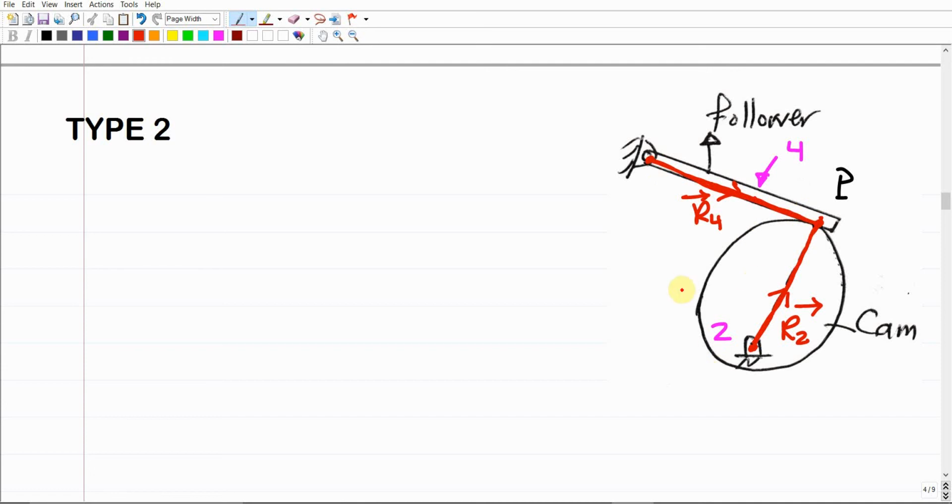So we're going to end up with a loop, but this loop is still open. To close the loop, we have to set up, or assume, this R as the R1 position vector. So we end up with a loop that includes three position vectors: R1, set up between the two fixed points, the fixed point of the first object and the fixed point of the second object, and R4 and R2, which are the two other position vectors.